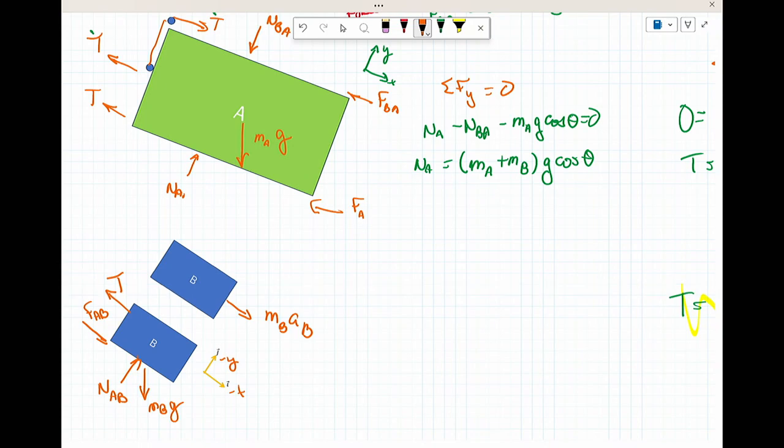One thing hasn't changed. This thing is still not jumping or bouncing. And so sum of forces in Y is still going to equal 0. So I have all that. And this is just equals. So this is your kinematics. I don't always draw the kinematic diagram, but it's useful to remember that. I'm just setting up Newton's second law so I can look at it.